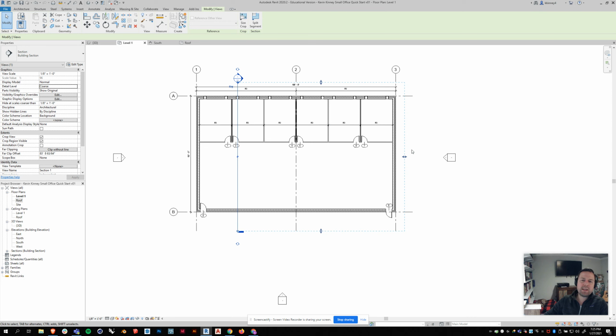So for example, if I did it to here, this room would look exactly the same in my section cut, but this room would be shortened because I'm not seeing that back wall. So I'm going to keep this all the way down there. And maybe I'll put my section here, kind of clean this up a little bit. It's kind of nice that my numbers up here and the section marker line up there.